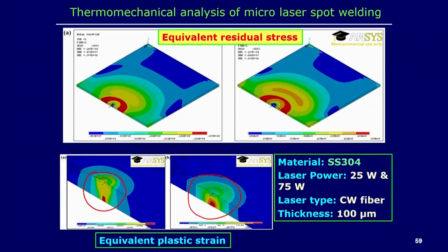So, here you can see in what way the residual stress is distributed in the case of the welding process. Of course, this residual stress is calculated once the heat input is removed, that means after solidification happens and it comes back to room temperature. Then this is the permanent amount of stress, strain or distortion field that is actually generated in the welding process. These are the typical distributions.